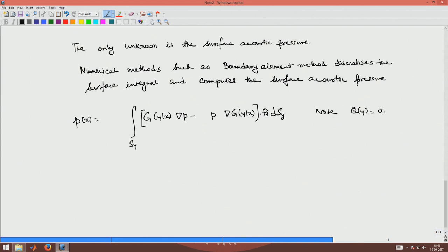because we are not considering any source which is outside this vibrating body. So, as a result of this, please note del p dot n is known. I should have taken the dot n inside. So, del p dot n, which is related to the surface velocities, is known, because the vibration velocity on the surface is known through a vibration analysis.